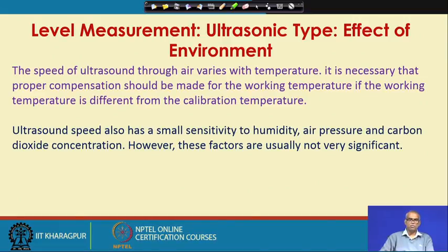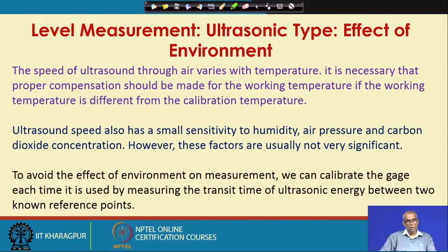However, this dependence is very small. So, these factors are usually not very significant. So, they do not invite much error in the calculations or in the level measurement. But to avoid the effect of environment on measurement, we can always calibrate the gauge each time it is used by measuring the transit time of ultrasonic energy between two known reference points.